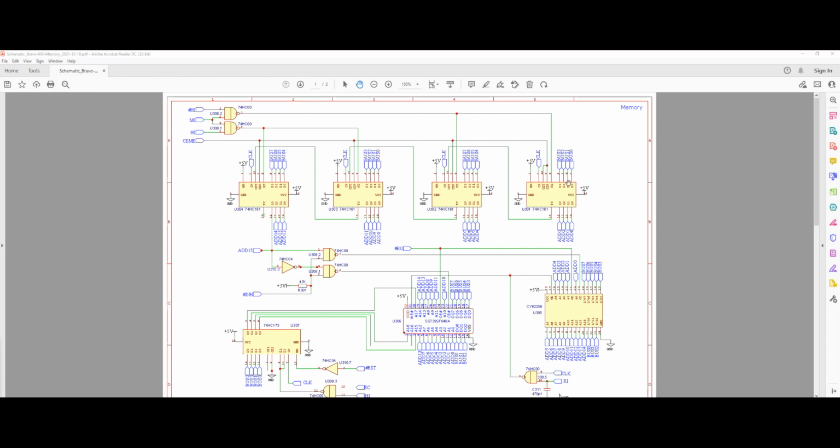Therefore, if we want a 16-bit input into this circuit, we need to do it in 2 cycles: first we read a value into the bus, and then read it into the low byte side of our register, and then we write a value to the bus again and read that value into the high byte part of the circuit. This way, using 2 cycles, we are able to read the whole 16 bits that we need as an input to our